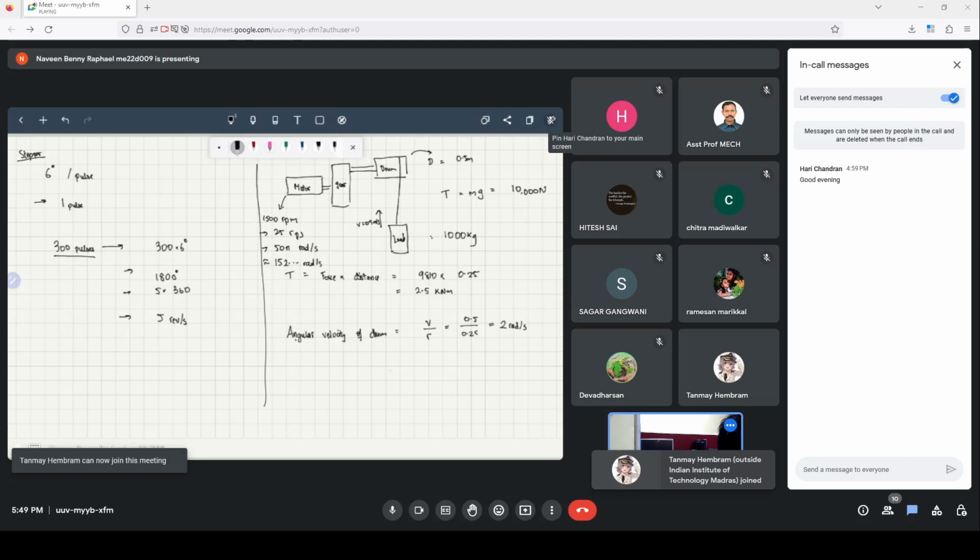When you divide, that means the gear ratio is like 152 point something divided by 2, which is actually 75, but the textbook decided that it's fine to round up, and we get a gear ratio of 1:80.